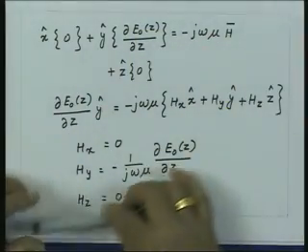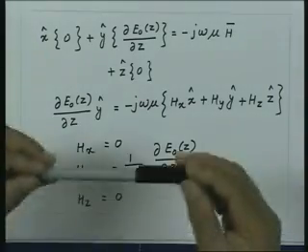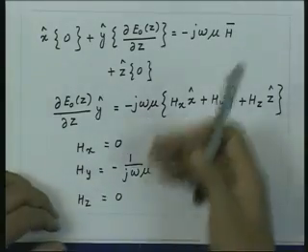Exactly what we did, the plane which we have considered here is the xy plane. In that case, in that plane the fields were constant. We could have done the similar thing for the xz plane also, and we would again get a solution for which the field will be varying now as a function of y, and that's why you will get again a similar kind of expression for the magnetic fields. So, we can say now in general that if the fields were constant in any plane containing the field vector, then perpendicular to that plane the fields have a variation, and the electric and magnetic field will coexist in this medium, and that's why for time varying fields this is the simplest possible solution.